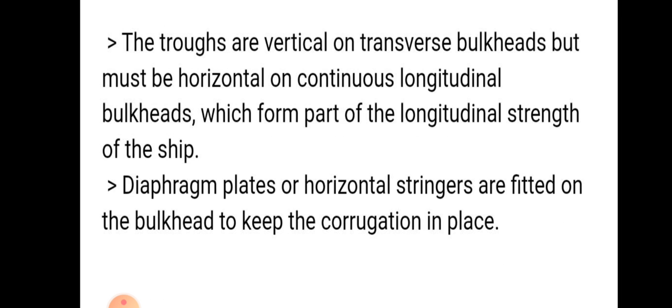The troughs are vertical on a transverse bulkhead, but must be horizontal on a continuous longitudinal bulkhead, which forms part of the longitudinal strength of the ship.